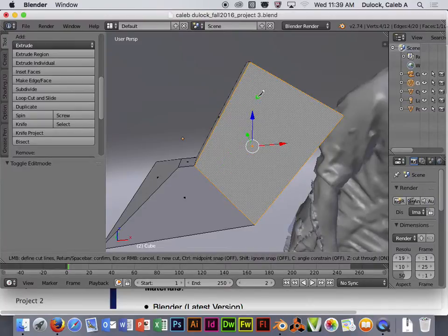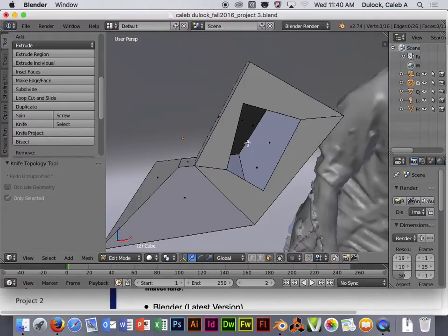What I can do with it is draw a basic polygon structure on top of a selected face that I have in my scene. It shows little green dots to indicate where I'm allowed to draw. And it works kind of like the pen tool in Illustrator. So if I click, it'll drop a point and then extend a point out from it. I can draw with it to make either incomplete shapes, or I can close it in to make a complete form by moving it back to where I started, and then hit return to complete the work.